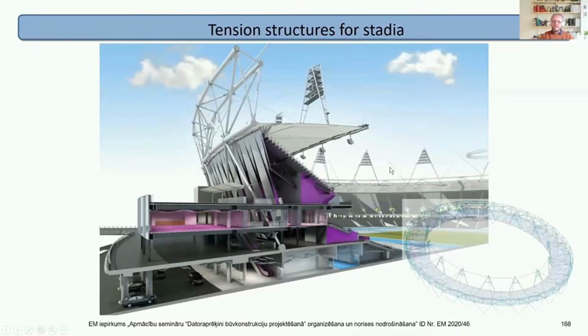If I bring up the analysis model, you can see this cable on the inside is like a bicycle wheel. It's sort of held in place by its tension against the tension back. So the roof parts are nearly horizontal, a little bit of downward slope, but not much. But it's essentially a balance between the tension in the cable outside and the tension in the cable pulling it in the opposite direction.